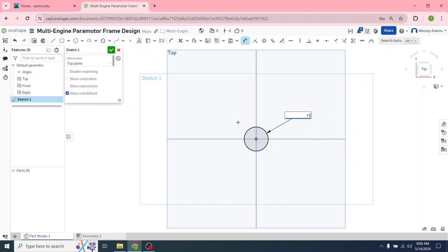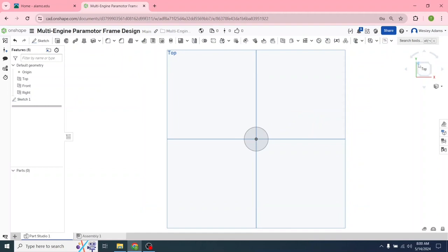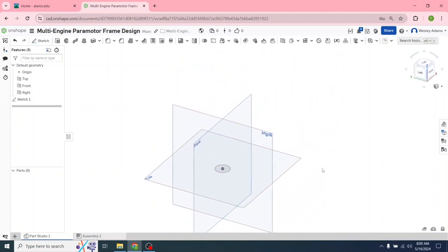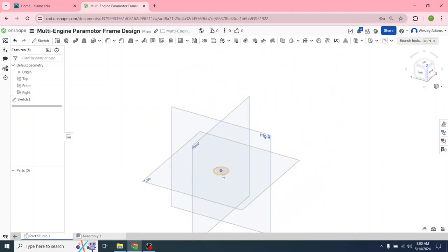All right, go over to sketch 1, left click. Go over to your navigation cube, left click. You can just click on the outer edge. That's all we need to see. Now we have two different tools we could use. We could extrude, or we could sweep. We're going to use sweep, so we need another sketch.